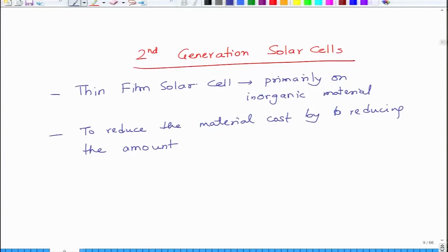Since the 80s onwards vacuum technology matured, that is why thin film technology also got superior, and most of the thin film devices also got a kick, because of improvements in the vacuum technology and equipment. You could make cleaner materials in thin film form. In thin film form, the cleanliness is very important, because if a small dust particle gets in which is of the same dimension as the thin film, your thin film will be dead. So that is why you require a very clean atmosphere for thin films, and that is why vacuum is preferred over air.